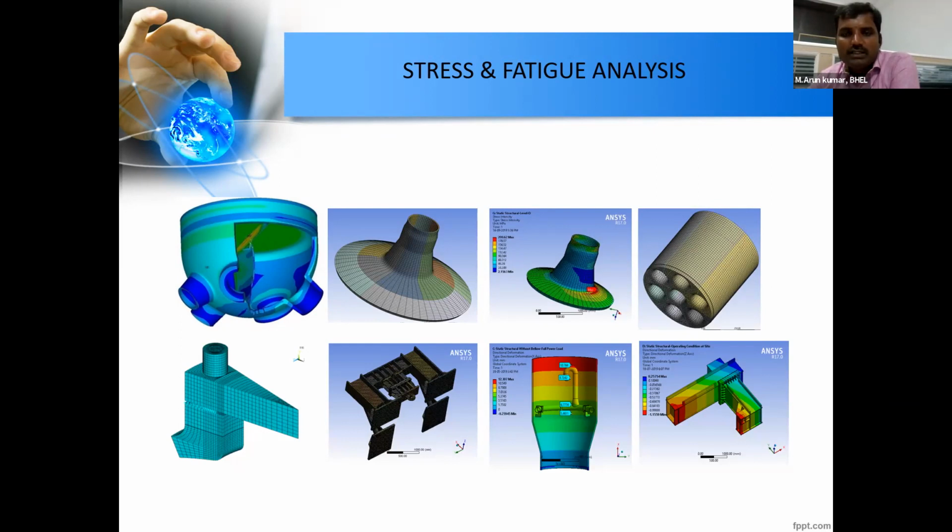Here we are restricting the aspect ratio to close to 1 or up to 5. Even though the program or FEM allows up to 20, we are restricting it to 5 only. And not only that, we are not going for any major assumptions during this analysis. We are modeling everything, creating the complete finite element model.